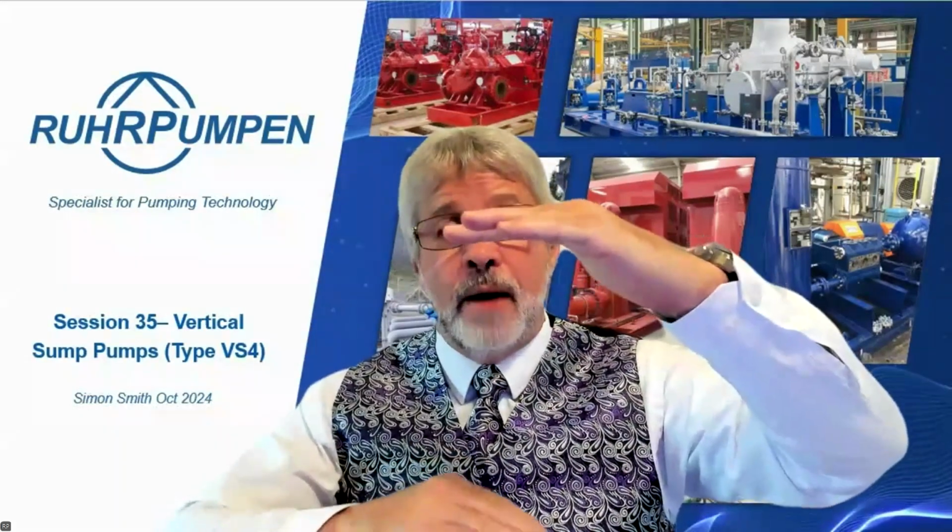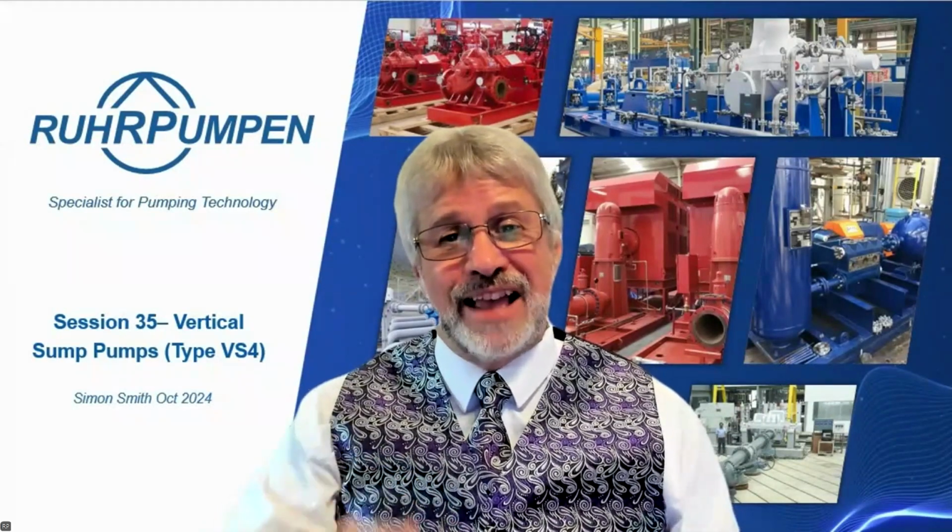Nanatambi Damalingam, excuse me if I've messed up that pronunciation. Can you please explain a little bit on NPSH requirement of this pump? We would be, as manufacturers, checking that the NPSH requirement is met on the pump. What you need to do is ensure that there's sufficient head of liquid above the impeller to make sure that it operates without cavitation. So when you send us the details of the job, we would know the vapor pressure of the fluid, we'd know the temperature of the fluid, what the fluid is. We would be able to establish what the NPSH available is, and we would then tell you what the minimum liquid level has to be to pump suitably, keeping a suitable NPSH margin.